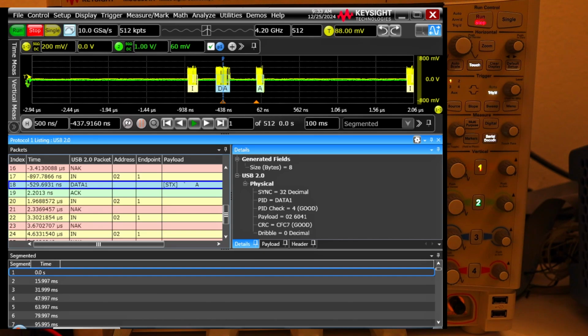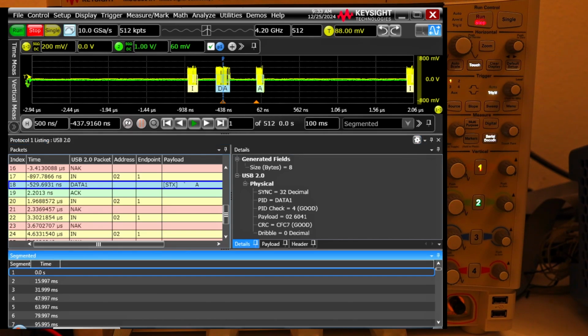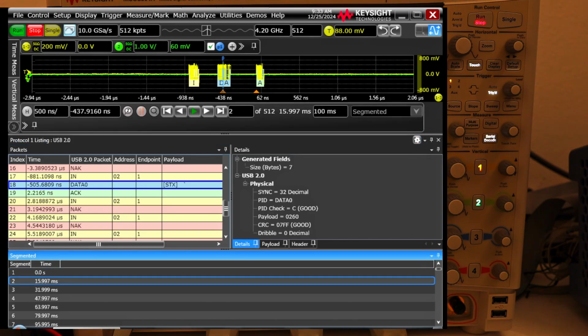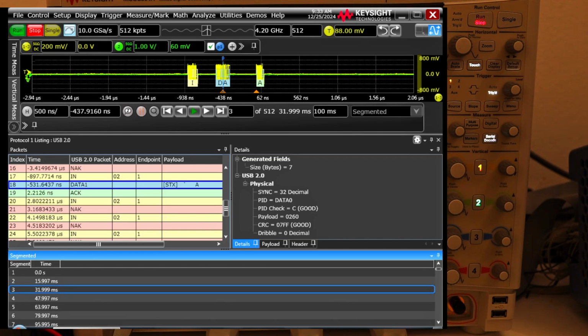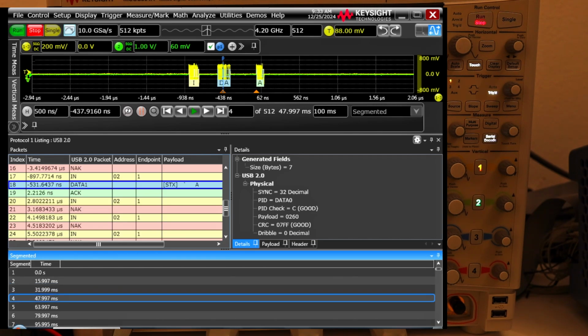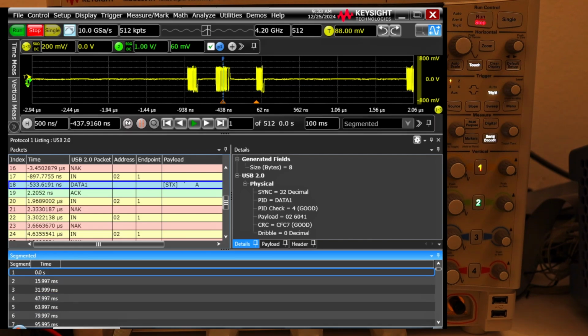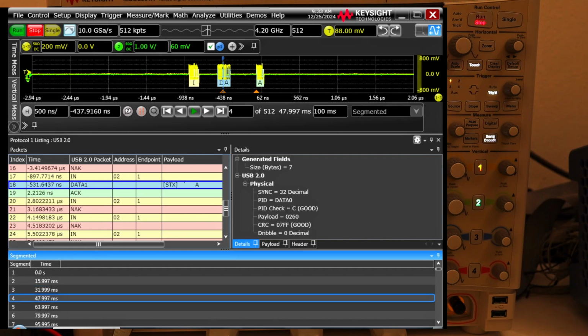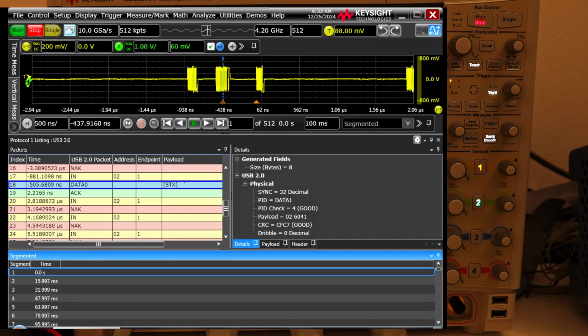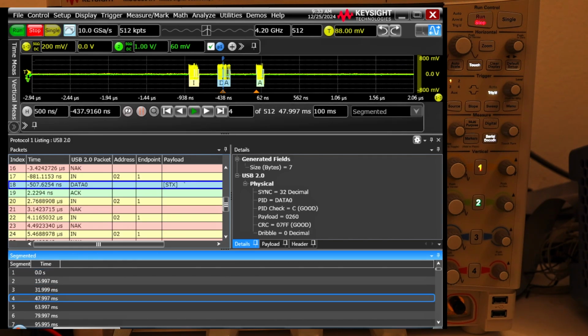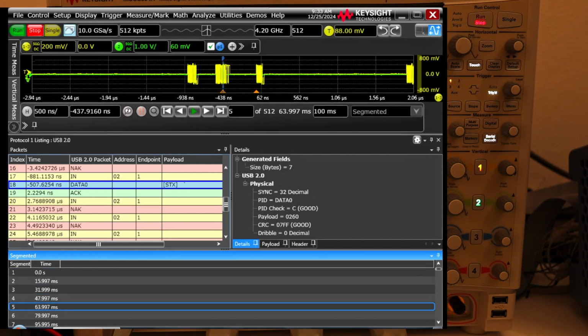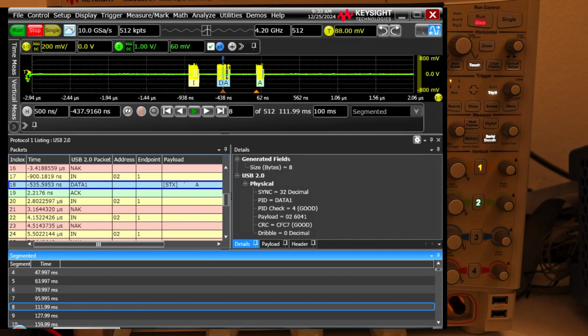As I'm pressing on the keyboard, at the 0th second, it got detected. After 16 milliseconds, there is no A in the packet. After 32 milliseconds, again not there, again there. So I'm repeatedly sending A, and alternate packets have my content. I'm pretty sure that FTDI sends this 0260. I do not know what 0260 means, but it definitely sends 0260 before my data. That's what we are going to trigger on.